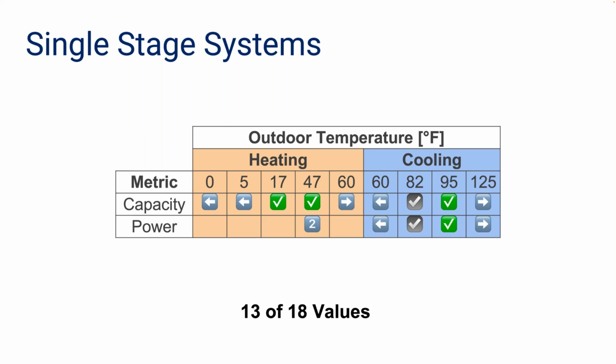And if it's not, then we start over. We put in another guess, so guess number 2 here. We do the same process, we check it, and you keep on going until eventually, with more informed guesses based on previous guesses, you get to a point where it matches, and then we can move on. And what we've done now is we've established a full performance map that is consistent with all of the AHRI certified data that we have available to us. If you were to synthesize the AHRI testing procedures for this model and run the calculations, you would get the exact same HSPF2 and the exact same SEER2.